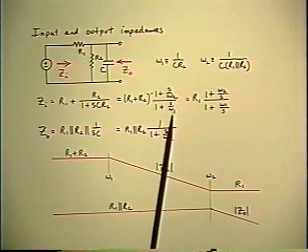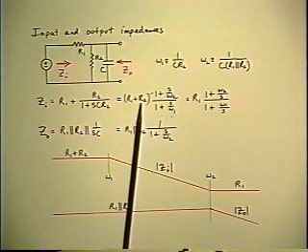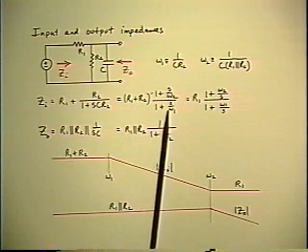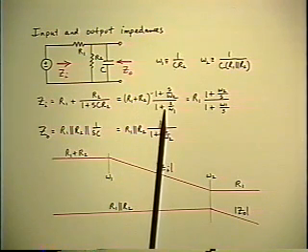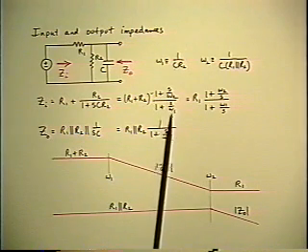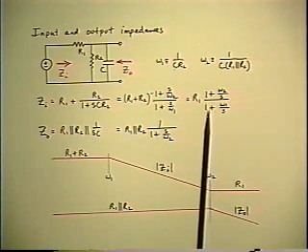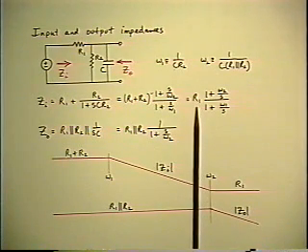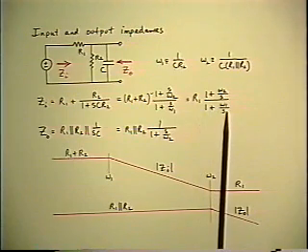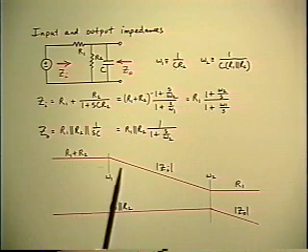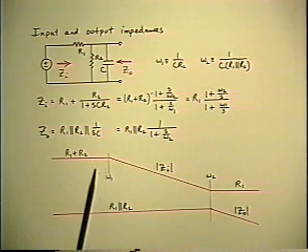In the normal pole zero form, the coefficient in front, R1 plus R2, of course, corresponds to the zero frequency value of the input impedance. But because we have a pole and a zero, it's just like the lag-lead network, so you have an alternative form. You could use the infinite frequency impedance as the coefficient in front with an inverted pole and zero. Algebraically, it's easy to get from one to the other. Here's the sketch that goes with it.